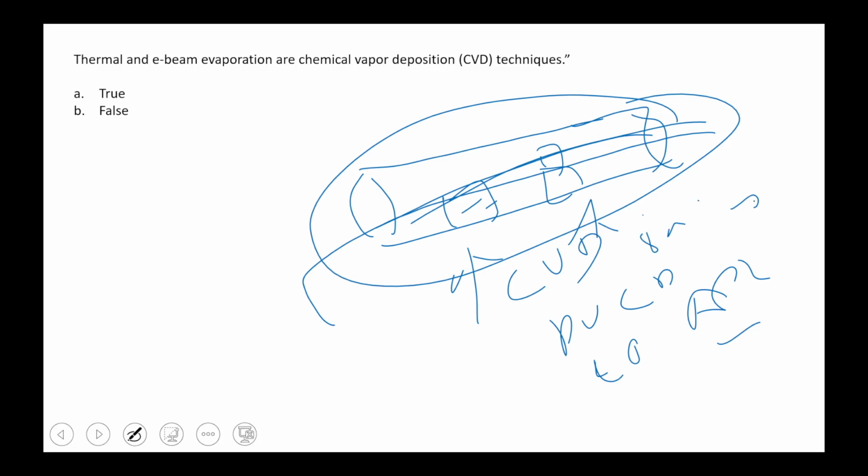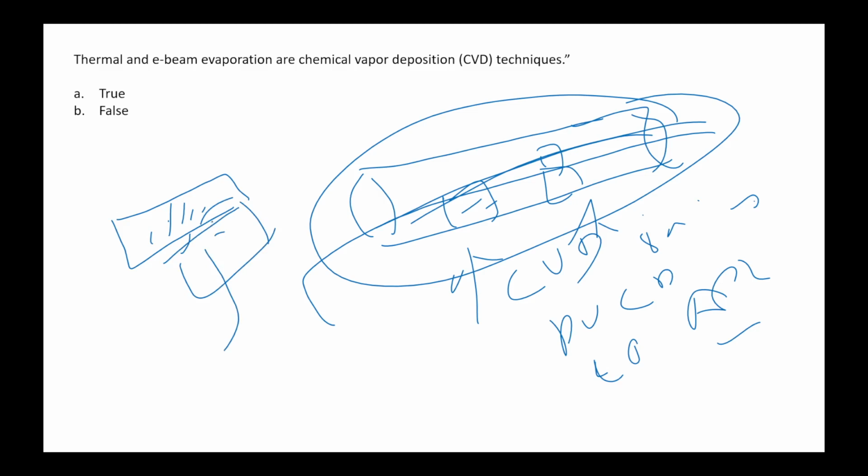In thermal evaporation systems, in place of heating, we supply some current. We have a boat, like an aluminum crucible. We put the materials there and apply current. During the current, the crucible heats up and evaporates the materials.